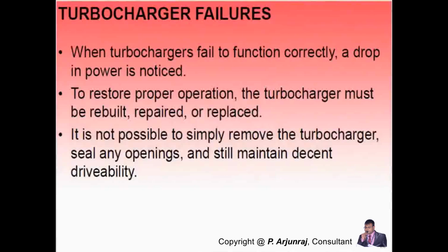If you're not controlling the wastegate to the required level, then it also creates the issue of loss in the system, or this will also contribute to higher fuel consumption from an efficiency point of view. And again, it will be fine tuned to operate depending on the required power. Yes, you need to do some fine tuning as well, and for that you need to calibrate your engine. You need to do some calibration, where the calibration role comes into the picture.